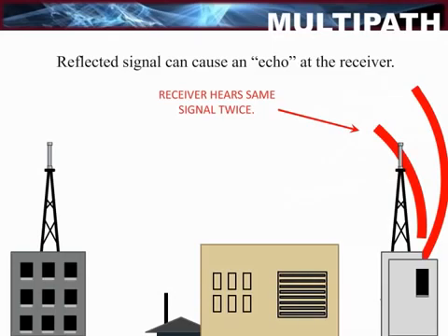Just as inching forward in your car at a stoplight helps the radio station come in better, simply moving either of the involved transceivers can improve the performance of the link if multipath is suspected. Changing the channel of the link can also help, as different channels have different wavelengths, and therefore different multipath effects.